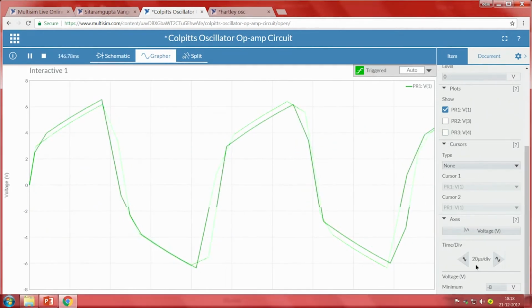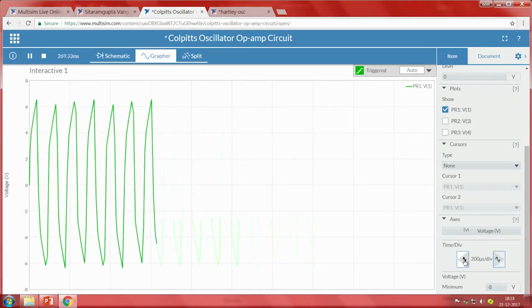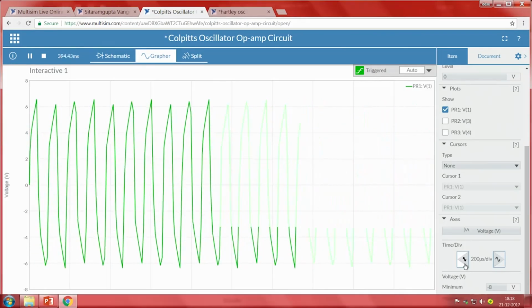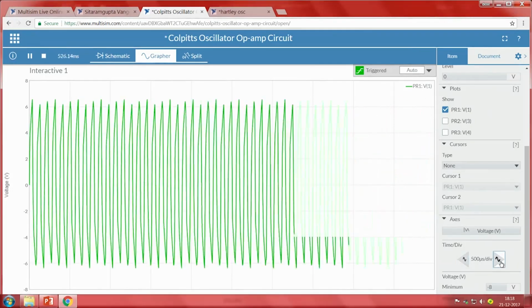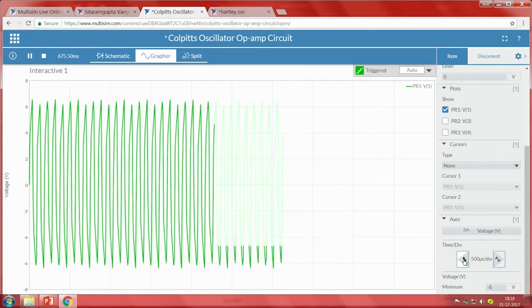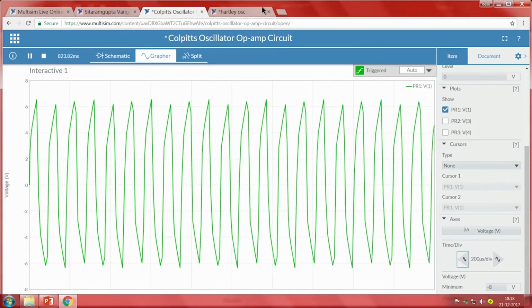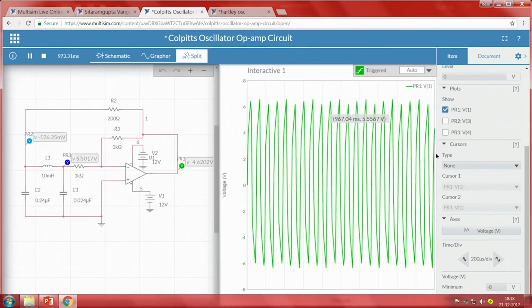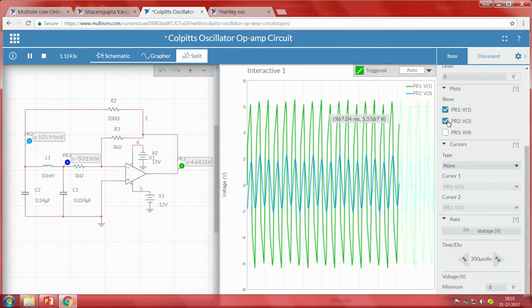then I can again change it. So, you can see here the oscillations are there, again you can change the time per division to get a better idea. You can play with the tool and you can see that by changing the divisions you can see the frequency increasing, or the number of divisions are higher, time per division is higher, and now you can see both the things simultaneously. You can also see the corresponding voltage at the output and how the oscillations are occurring with respect to that